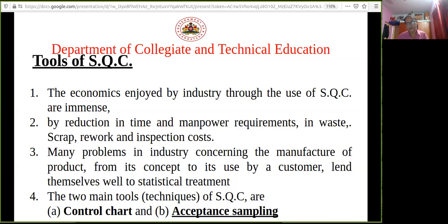So that process will be continued. When the manufacturing starts, the inspector will select, say, 5 items, and out of those 5 items, if 3 or more are good, then the customer is going to accept the lot. Even if 95 items out of 100 are bad, he is going to accept, because there will be other conditions here.